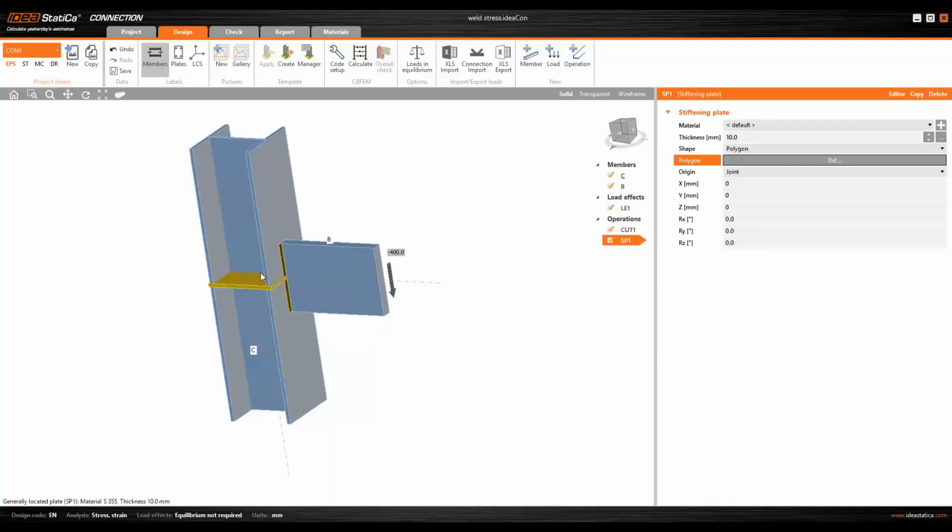So if your drawing is in millimeters, you have to switch in the import window, as Adam showed, to millimeters, and if you are in meters, you have to be in the same. Yes, we cover this transformation during the import, so you can do that. Of course, I also want to mention that you can import not only plates, but also different openings, different shapes of openings. It's also possible.